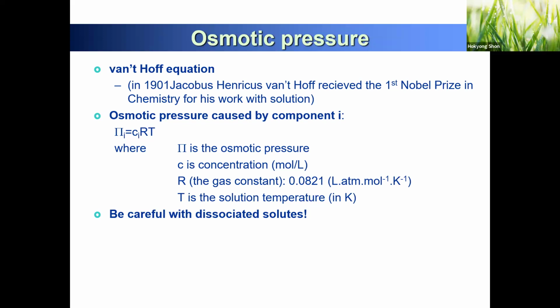So minimum you have to pressurize at least 54 bar for your applied pressure. You can also calculate how much water will be lost, and how much we can overcome your osmotic pressure. But based on that kind of calculation, you cannot do all the things.